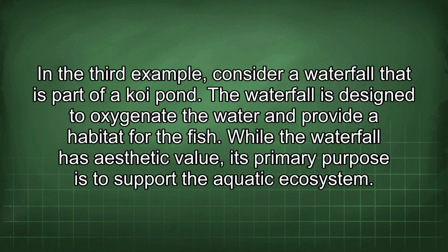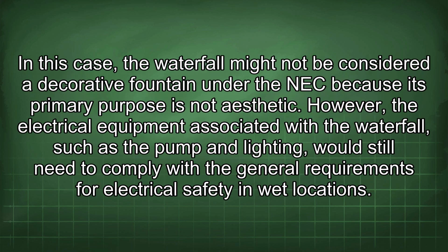In the third example, consider a waterfall that is part of a koi pond. The waterfall is designed to oxygenate the water and provide a habitat for the fish. While the waterfall has aesthetic value, its primary purpose is to support the aquatic ecosystem. In this case, the waterfall might not be considered a decorative fountain under the NEC because its primary purpose is not aesthetic. However, the electrical equipment associated with the waterfall, such as the pump and lighting, would still need to comply with the general requirements for electrical safety in wet locations.